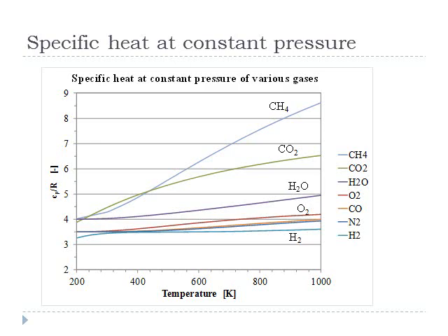Hydrogen is one of those gases where, over our range of interest, there's almost no change between 300 kelvins and 1,000 kelvins. So anytime you're dealing with hydrogen, you don't even need the linear correction. You can just treat hydrogen as having a constant specific heat. And in this case, what you see is the specific heat divided by R is equal to 3/2.